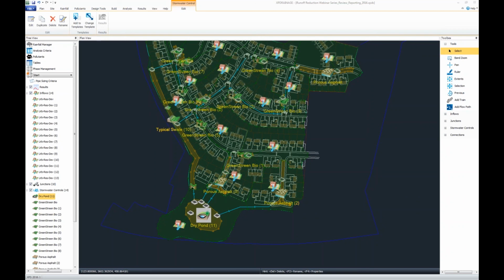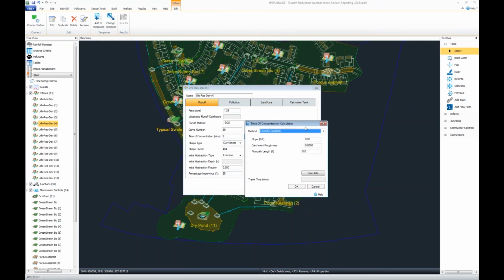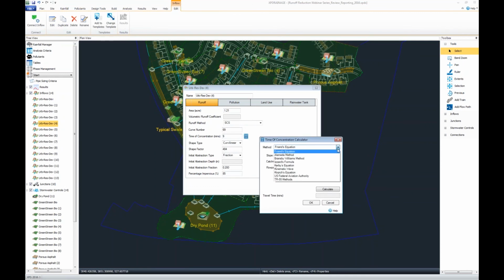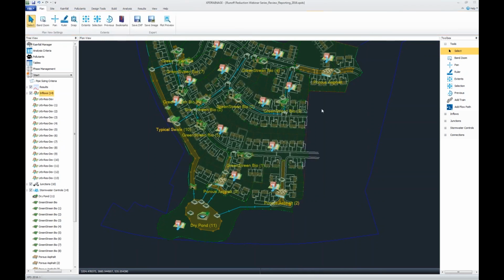So one question, how do I identify the curve number? There are a couple of ways you can do that. In this case, I simply defined the pervious curve number and gave it the percent imperviousness. There's also time of concentration, which goes along with the site description. There's a calculator for the time of concentration, and you can pick the different method, kinematic wave, what have you. Usually, given your land use and the percent imperviousness, you would have to weight that. There's no automatic tool to do that, so you designate what you have.